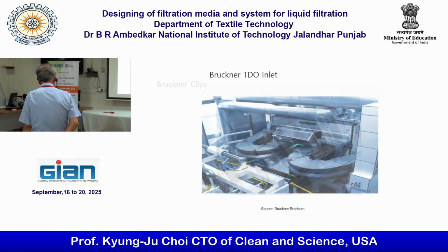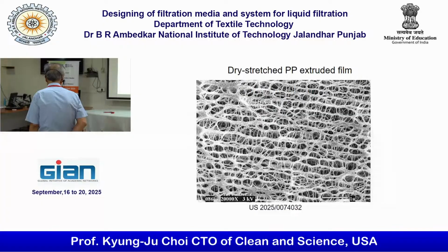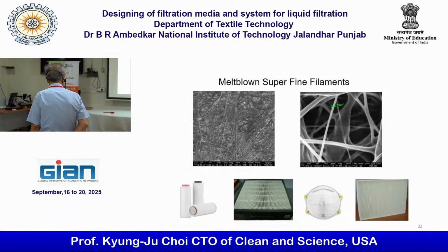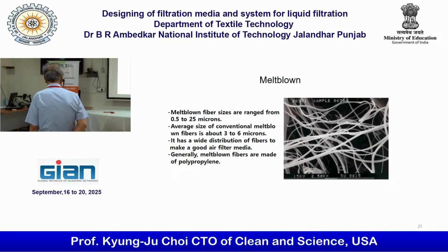I also have the melt blown machine patents, about 3 of them. So it really depends on the design. Then you can actually go down to 0.5 micron size melt blown. Normally, melt blown material, the fiber size has a big distribution in it. So if the fiber size, all of them are smaller, then pressure drop is going to fit. So combination of the fiber size, that's why pressure drop is lower.